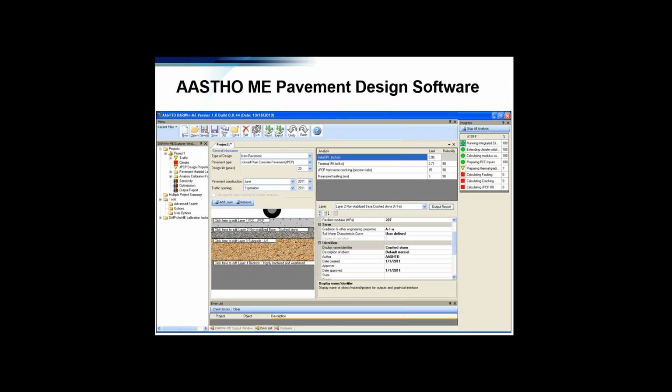Somehow the freezing index, the measure of frost depth, going into, I think, the rigid pavement committee model for smoothness, for IRI, had a bug in it. Somebody found that just recently. So never say never, I guess. But this whole thing of checking your work and correcting is really, really important in this day and age.